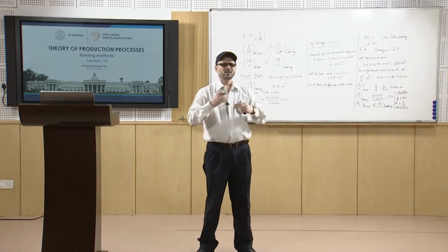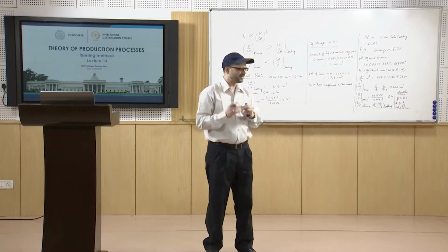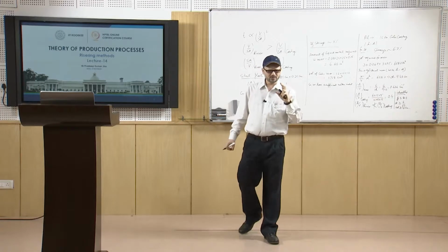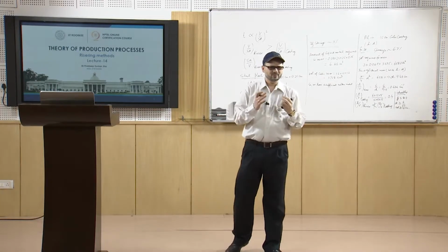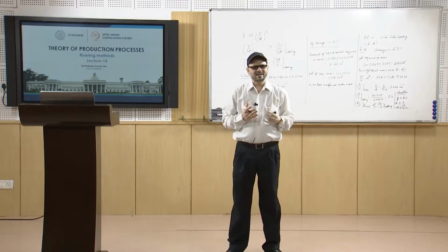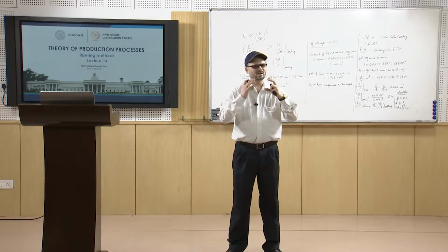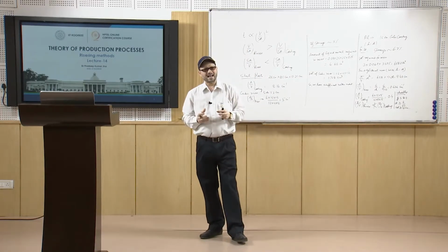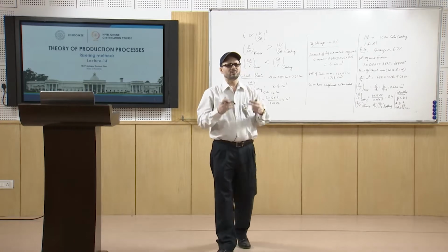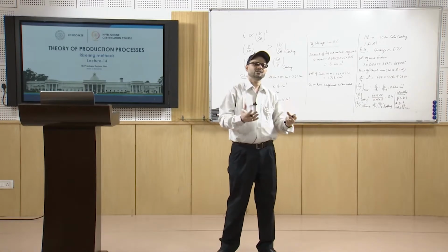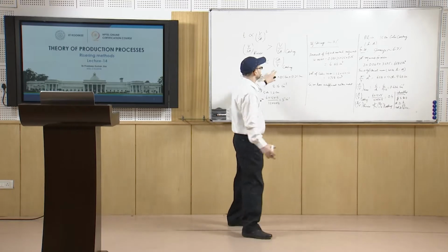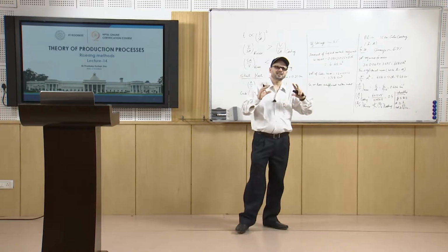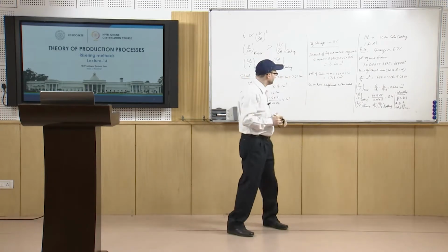So, what we see is that it is very important to have these conditions met, and it is also important to know that there are two requirements. One is the freezing characteristic of the material, which is important for calculating the dimension of the riser, whereas the volume must be sufficient, so that the riser can feed the liquid metal required.